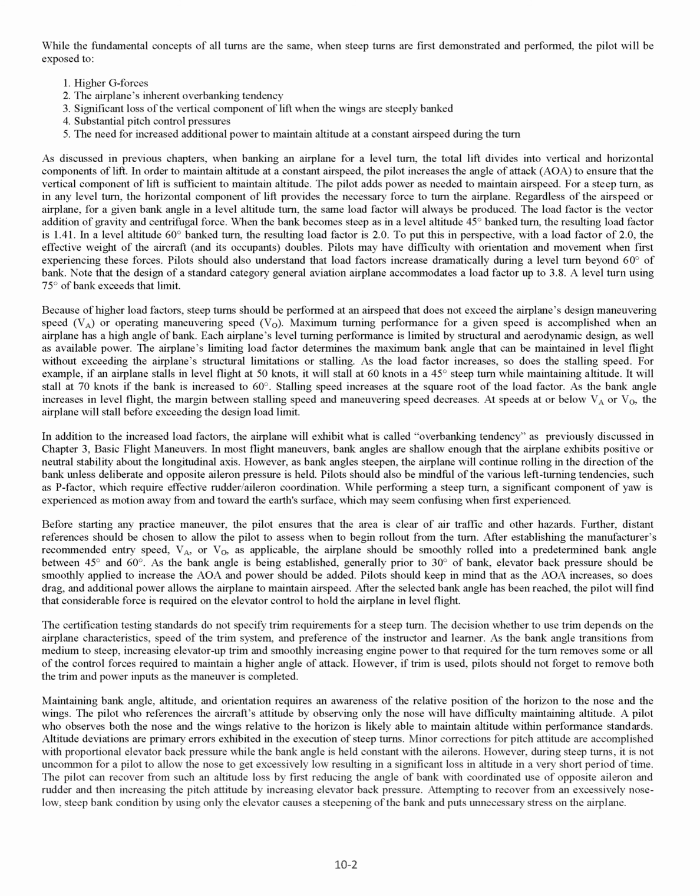For a steep turn, as in any level turn, the horizontal component of lift provides the necessary force to turn the airplane. Regardless of the airspeed or airplane, for a given bank angle in a level altitude turn, the same load factor will always be produced. The load factor is the vector addition of gravity and centrifugal force. When the bank becomes steep as in a level altitude 45 degrees bank turn, the resulting load factor is 1.41. In a level altitude 60 degrees bank turn, the resulting load factor is 2.0.